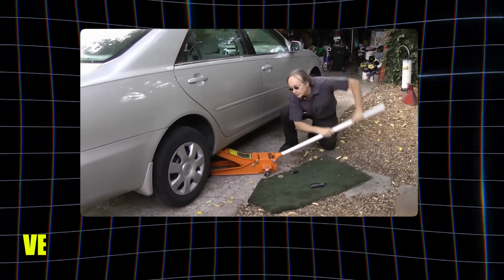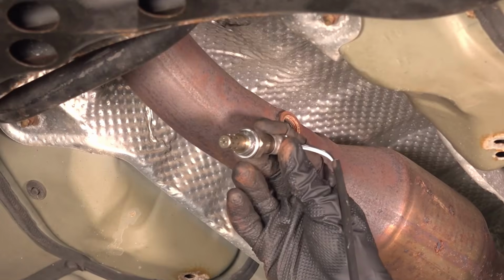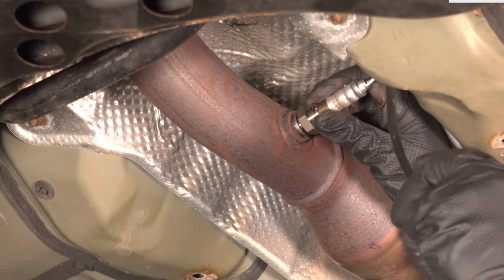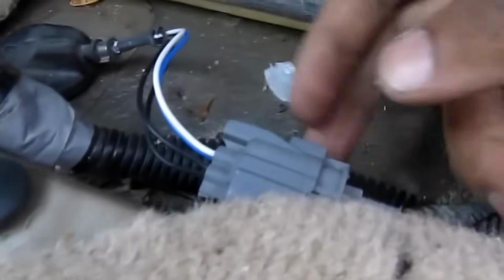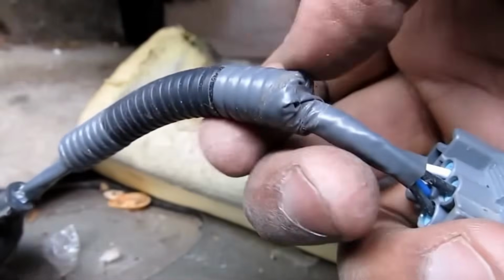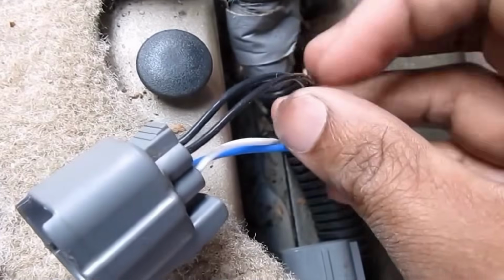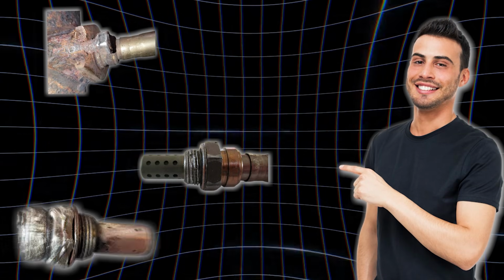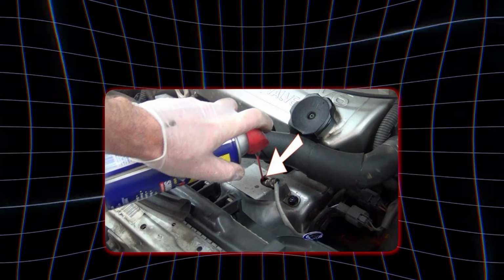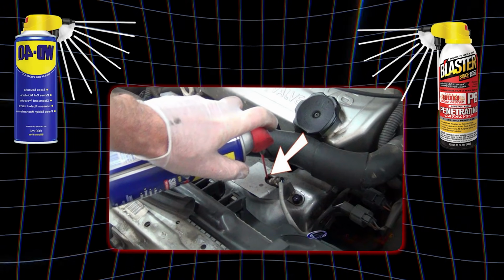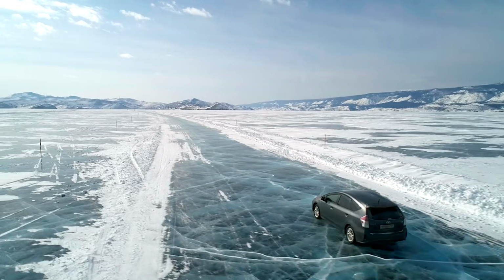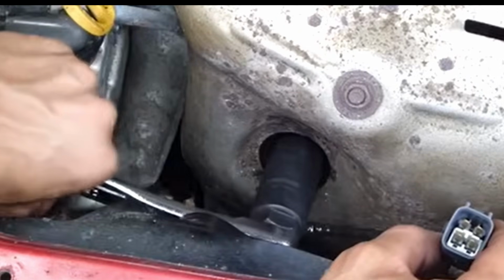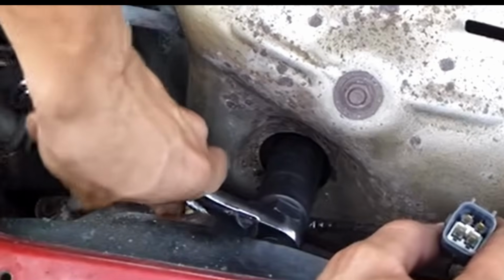Start by safely lifting the vehicle and securing it on jack stands, allowing easy access to the exhaust system. Once you locate the O2 sensors, typically near the catalytic converter, use the O2 sensor removal tool to unscrew them carefully without damaging the wiring or threads. During installation, you may encounter common challenges such as rusted, seized, or stubborn sensors. Applying a quality penetrating oil like PB Blaster or WD-40 can help loosen them, especially in older vehicles exposed to moisture and road salt. Be patient. Forcing the sensor can strip the threads or break the sensor altogether.